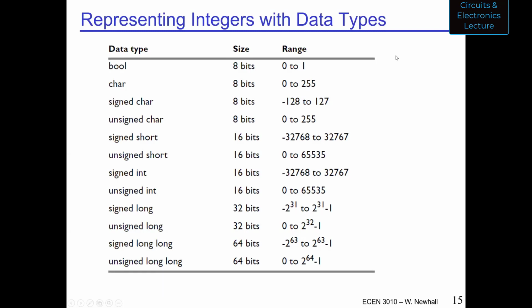If you use the Arduino IDE, you notice that in C you have to declare what type a variable is, like an integer or a long integer or a short integer, and what that's doing is defining how the compiler interprets the numbers and how many bits are in that number.